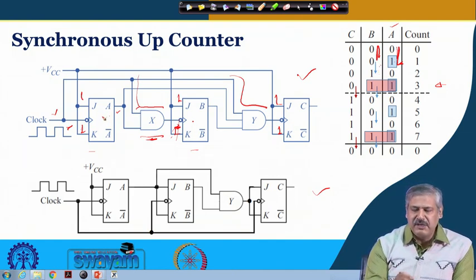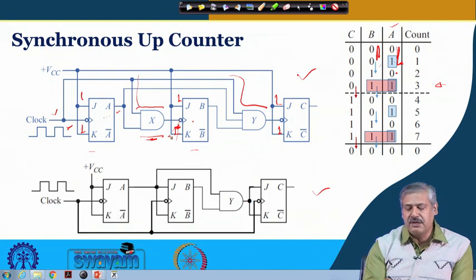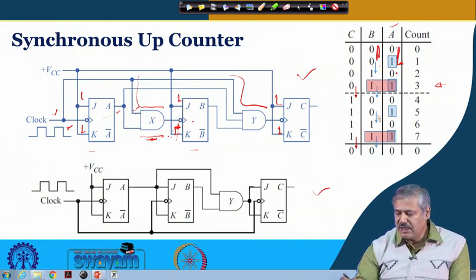So, then again A has become 0. When A becomes 0, this clock is not available, it is coming up to the AND gate input, so it will remain at the same value, because in that clock cycle there is no toggling happening. So this remains 1, 1, and this continues, that way it is 0, 0, 1, 1, 0, 0, 1, 1, again it will become 0, 0. So, that is for flip flop B.